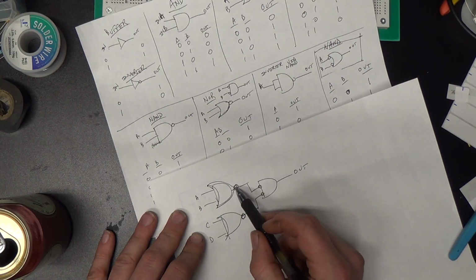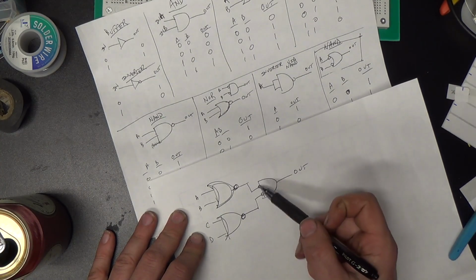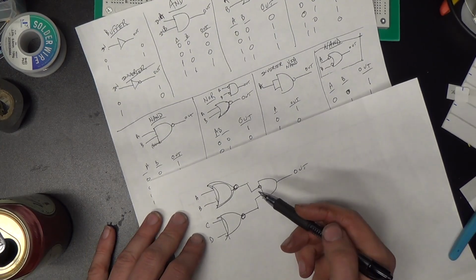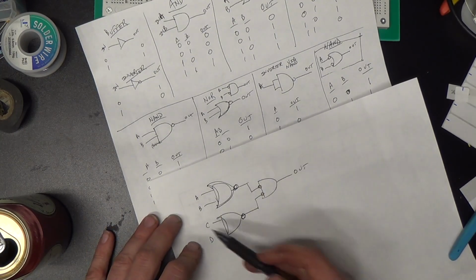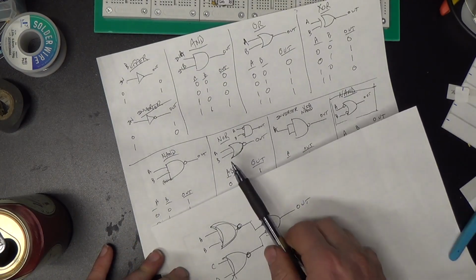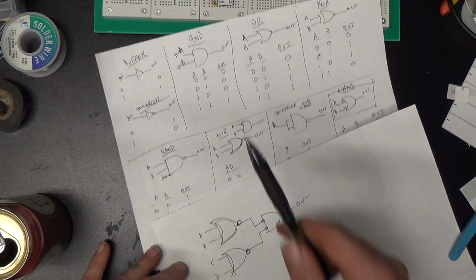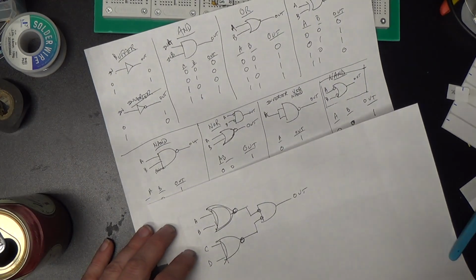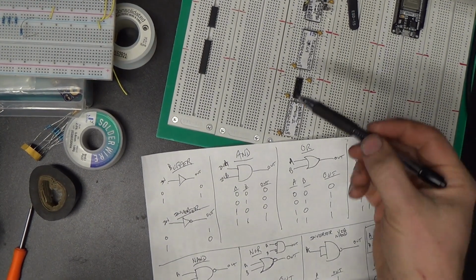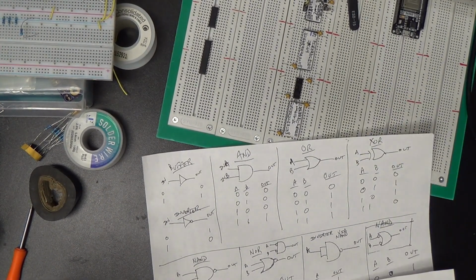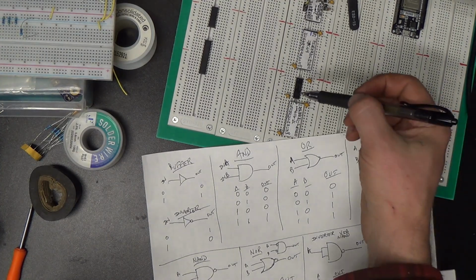So the signal goes through here, it gets inverted, but before it goes into this AND gate, it gets reinverted right back to what it was to begin with. So here we can do the same thing with a single chip that we would have had to use like 2 chips for up here. So that's going to be part of the basis for our address decoding for our RAM and our ROM up here in the